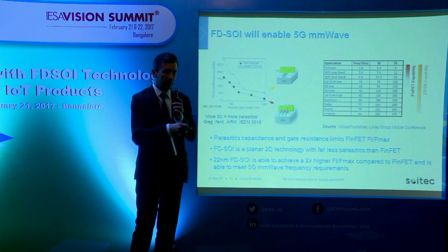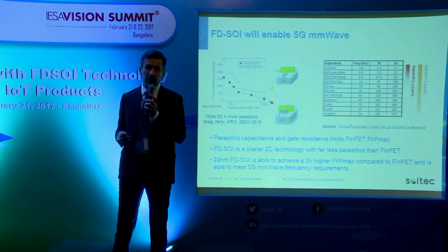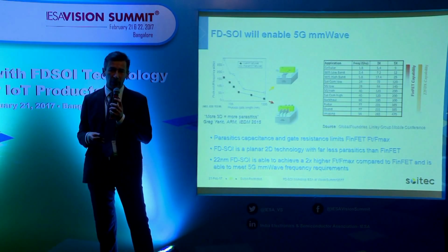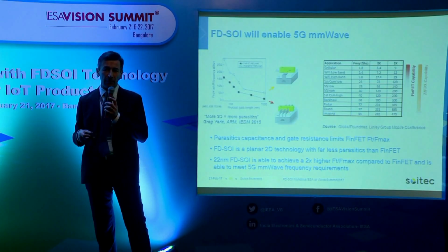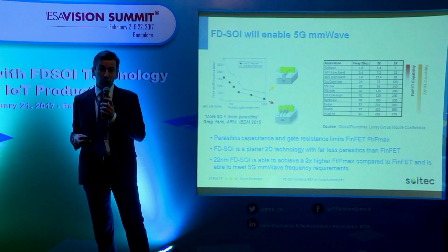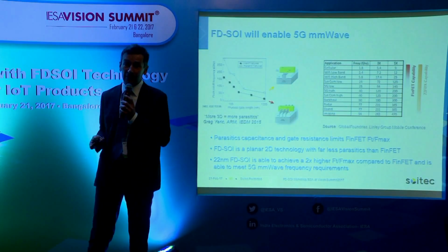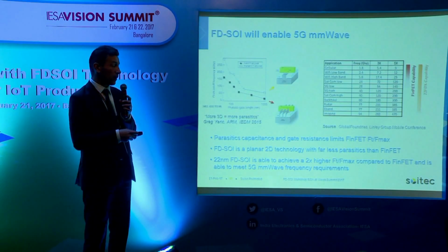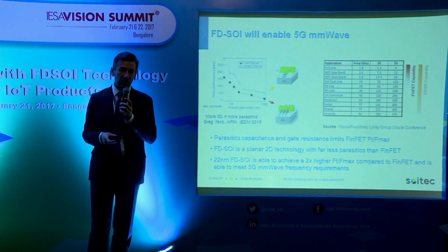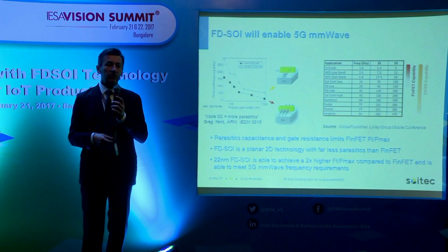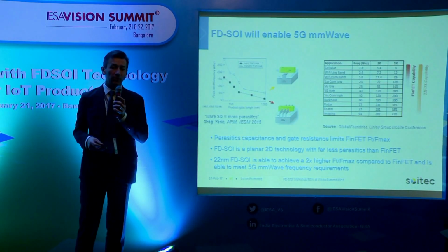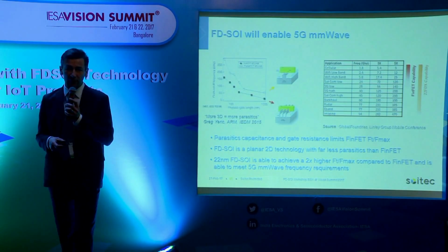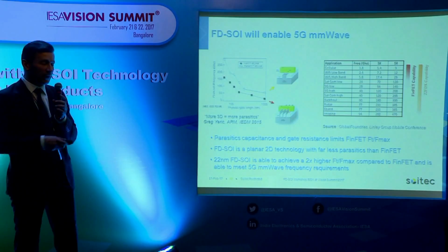FinFET can do some of that, but FDSOI today is the one which is going farther into the spectrum of all these new 5G applications. And from what we know and cannot really disclose in detail, several key fabless companies who are today setting up 5G applications and chips are already designing in FDSOI just because of this specific capability of FDSOI to handle these very high frequencies.